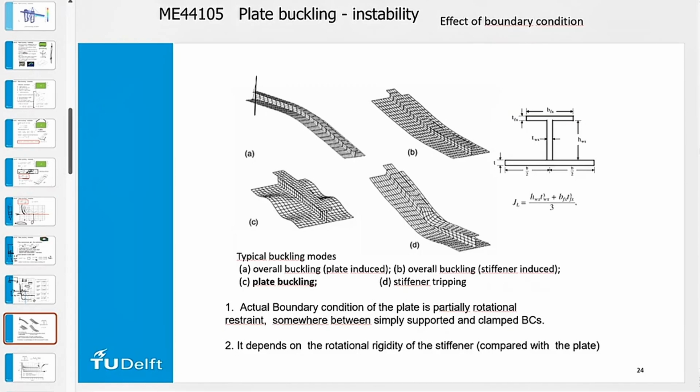I can assume that this is a beam, and I can calculate the buckling risk. But I need to take into account the limits for simple plate buckling, because of this limit of the other buckling limit. And we can now see, if we look at this shape, we can recognize, okay, this plate is at the beginning and at the end simply supported, but this one is free, and this one is free, and this one is simple